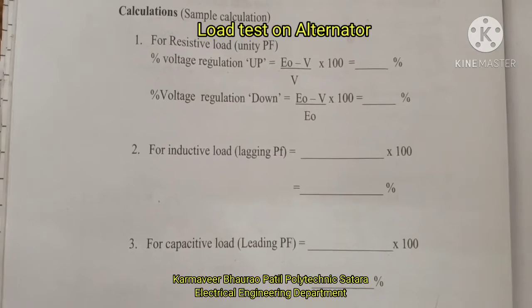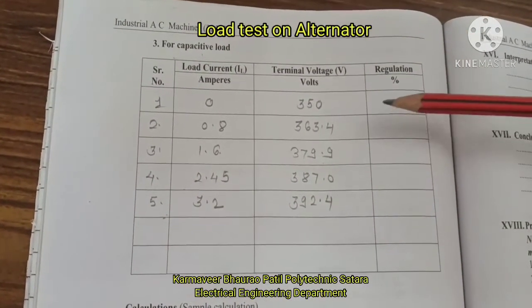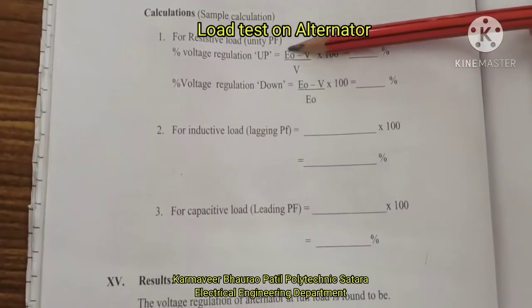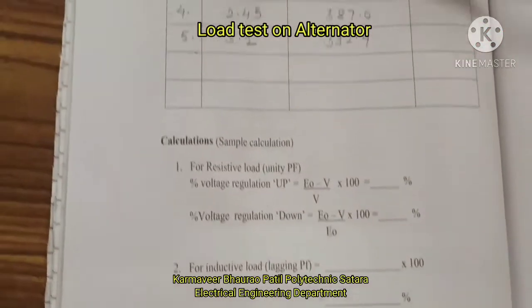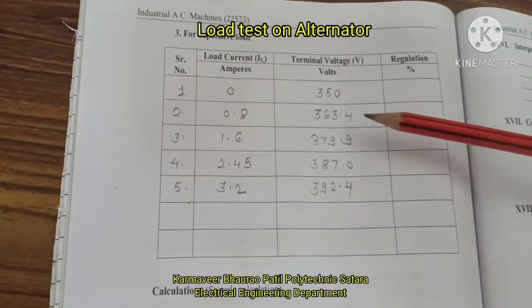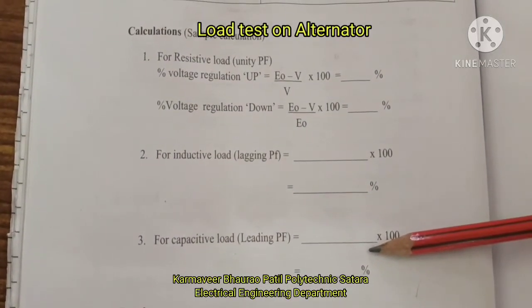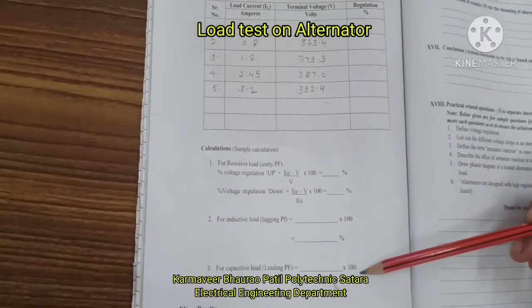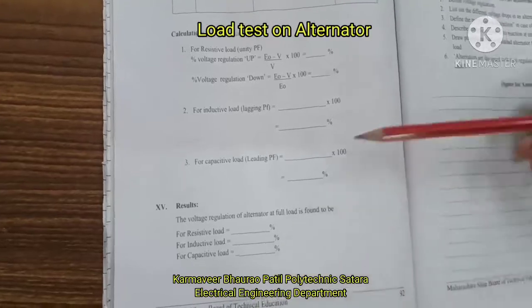For example, you can take the second reading, and with it you have to do the calculation for resistive load, inductive load and capacitive load. Put E0 as 350 and V will be, suppose, here 363.4. So the calculation will be 350 minus 363.4 divided by 350 into 100. So you get all the regulations; summarize them in the result.